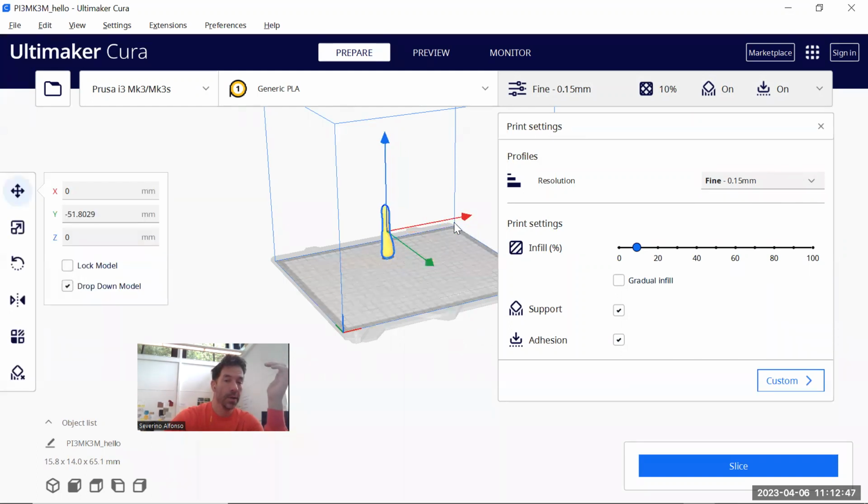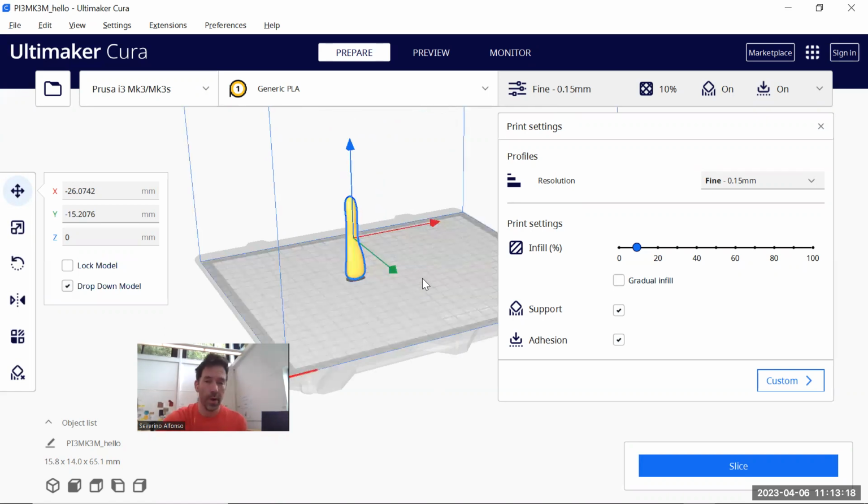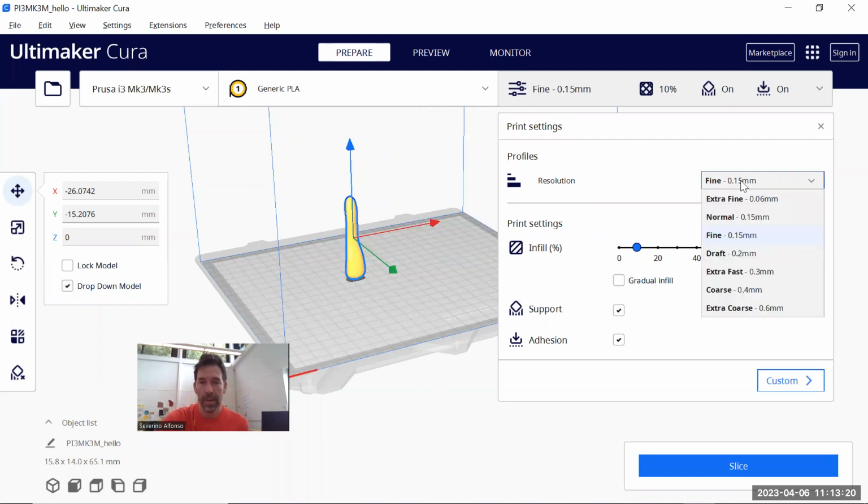But it can only print one thing at one time, obviously. It will go from the bottom and then slice upwards. So it will start the first bottom line of one of the pieces, then jump to the bottom line of the other one, and the other one, and so on. But you can go one by one, because it would just be an issue of time. Now, if you put 10 pieces here and one of them fails, you have to cancel the whole thing. And to be honest, it kind of fails quite often. So I would be careful.